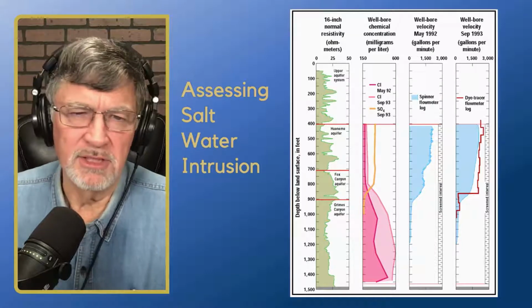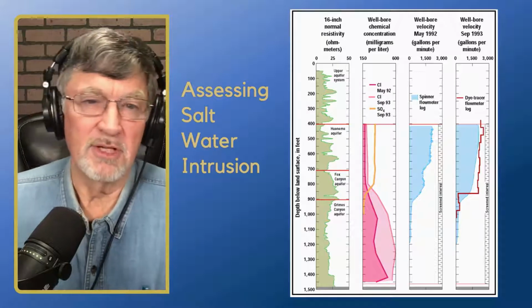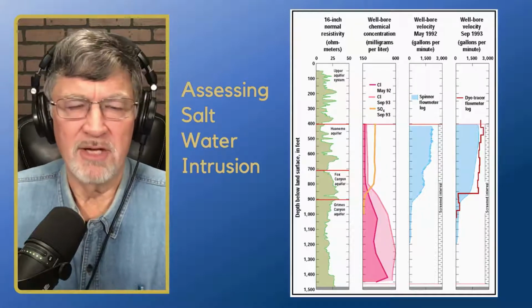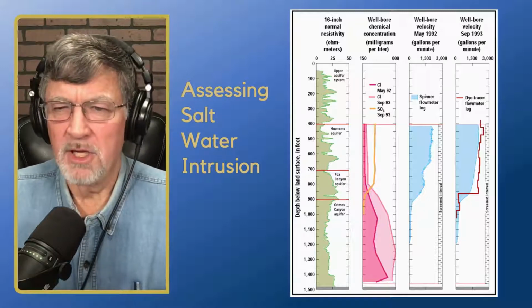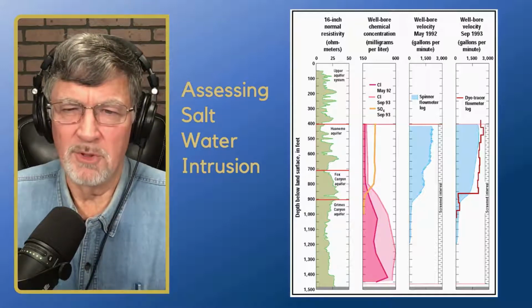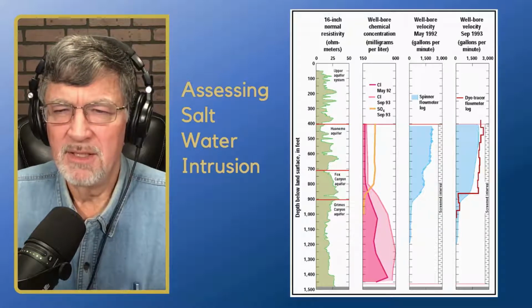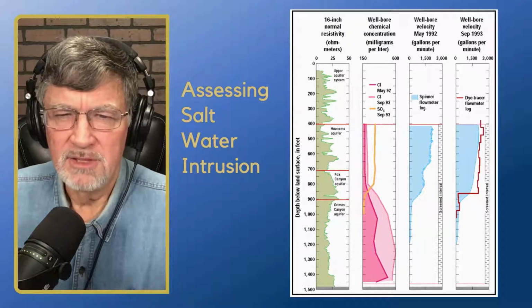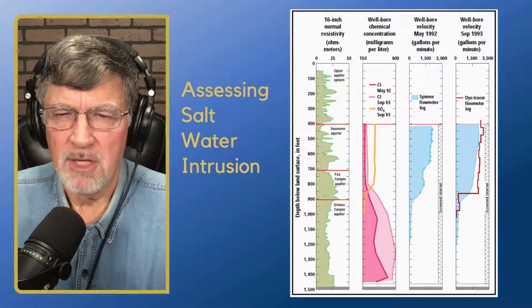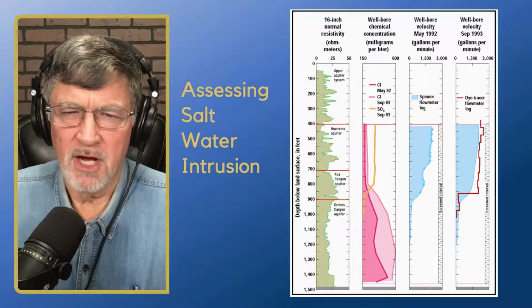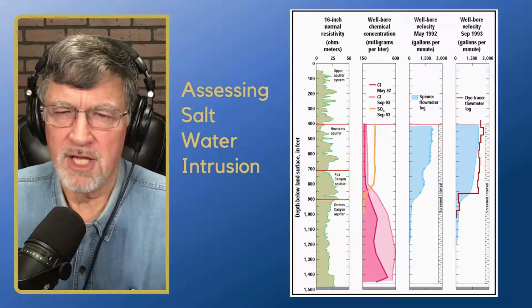So this is actually a good test. If we hadn't put in a well yet, we could design the well so that we're not really taking any of the saline water. We would probably develop our well partway into the section, maybe a quarter of the way. We'd seal off the bottom of the Fox Canyon aquifer and all of the Grimes Canyon aquifer.